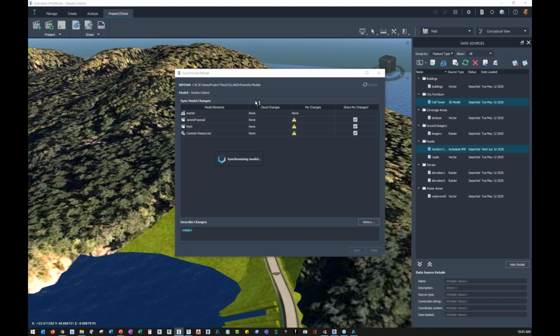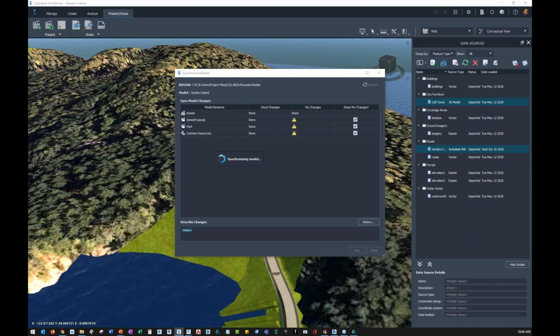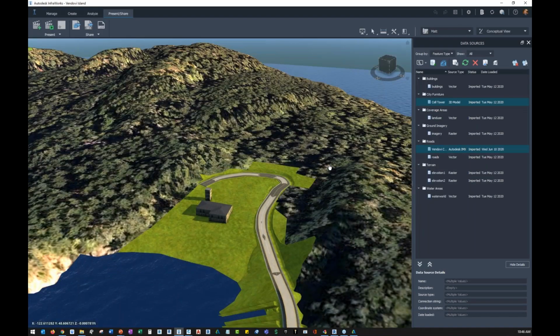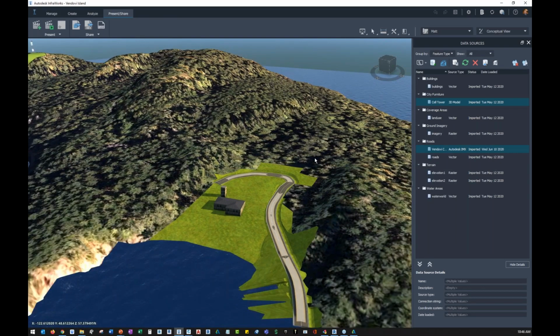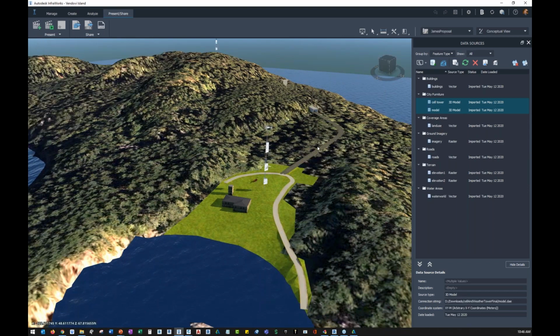So Infraworks does give you a little bit more of a dynamic collaboration function, but it is something that you need to synchronize manually. In this case, I'm clicking on synchronize to publish the information that I want, and I'm also clicking on synchronize to download the new information that I need to share. And there are not a lot of options in terms of whether I only want to synchronize certain pieces or everything. You're pretty much going to get everything that's in there, so it's not specific to the point of check boxes where I can choose specific items.